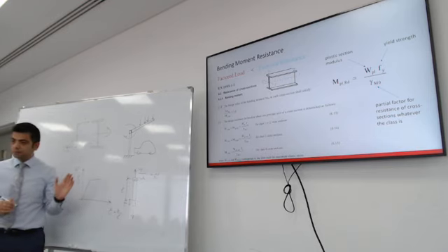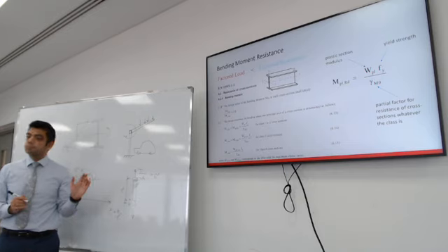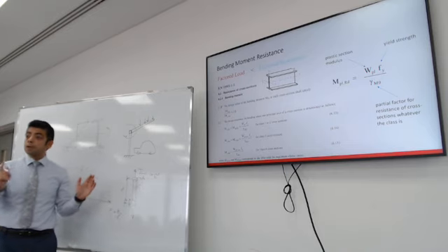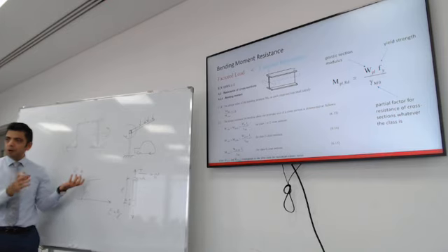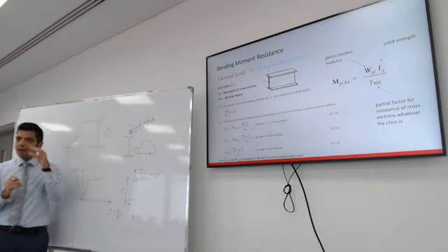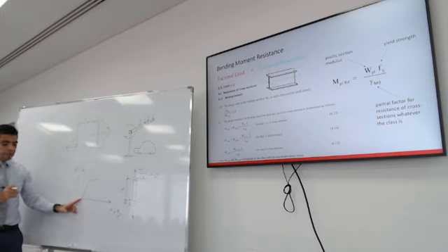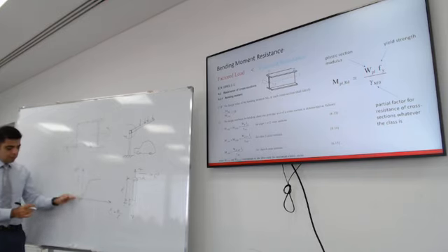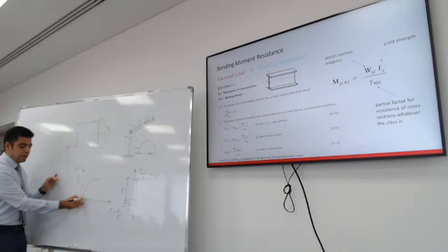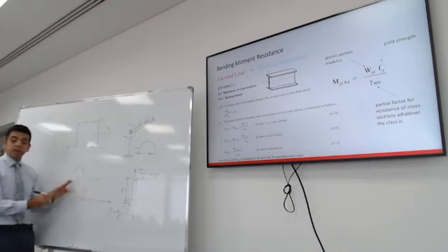Does that make sense? Yes, so we cannot use that number because I need to take a safety factor, not just use the steel to the actual limit. I need to take a factor of safety. So what I'm trying to say is, if you apply force in increments, the elongation or the strain will go linear up to yield.